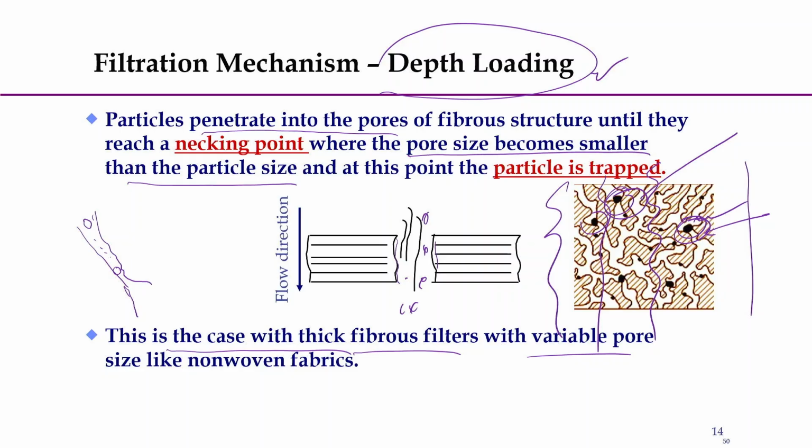If we want to reuse this filter medium, the cleaning of these particles which are trapped within the structure is very difficult. But surface loading can be cleaned by simply shaking or reverse airflow. So, that is the problem here. But for various applications like a filter, that is a face mask, where we do not reuse it, in those cases we need the smaller particles to be captured. So, there the depth loading principle is used.